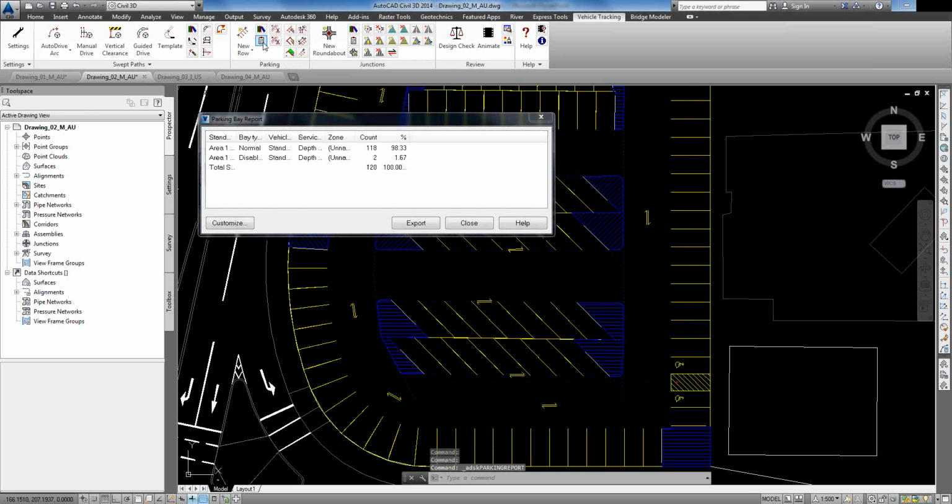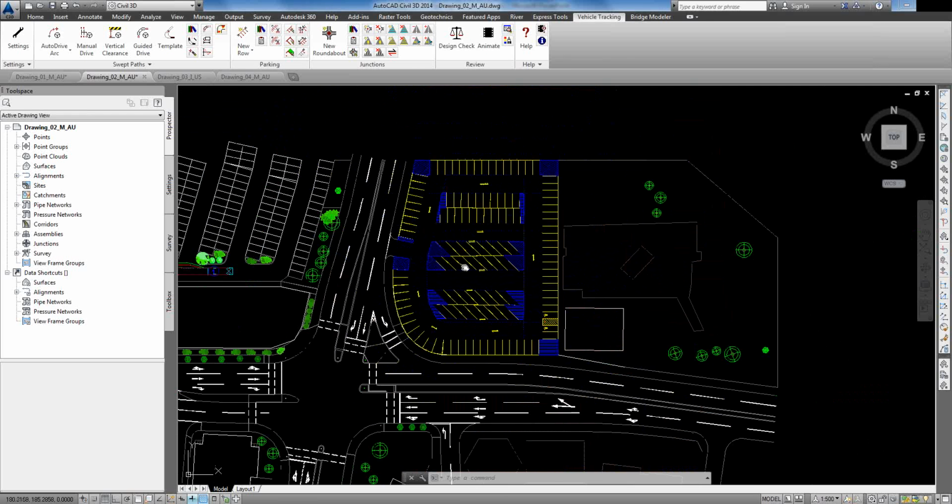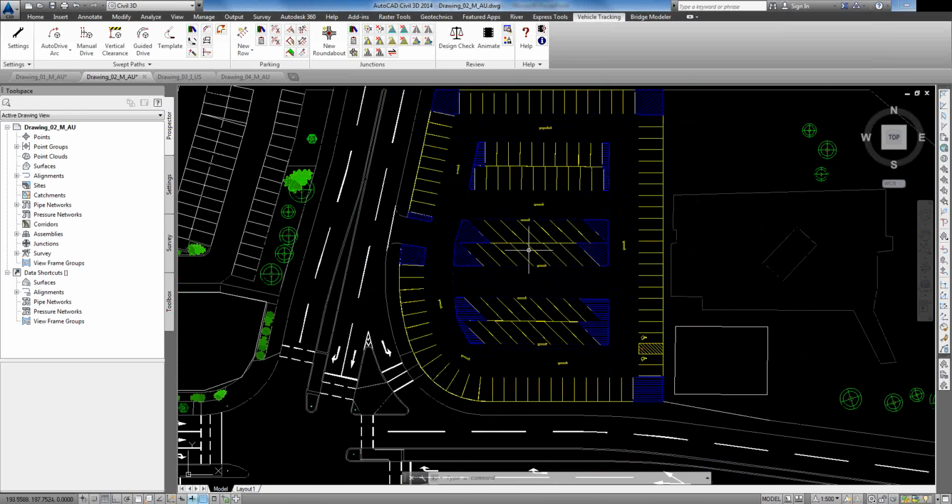of car parks we've got. So come back up to our report again, and our previous count was 137 with the standard vehicles, and we've also incorporated the disabled. Now notice, because we've put the angular contraflow parking bays in there now, we've actually reduced the amount of parking spaces that we have in there. Pretty cool. Really quick, you can model up different options and alternatives very quickly just by using all the different grips and the tools up here in the ribbon.